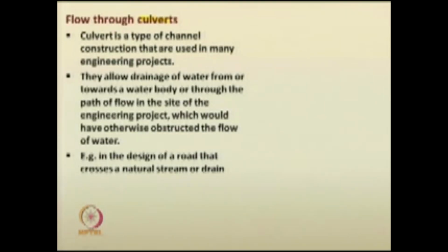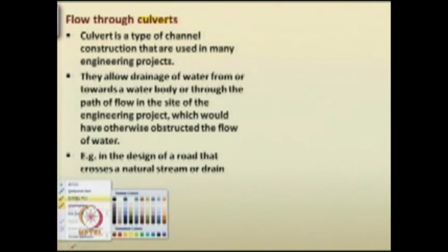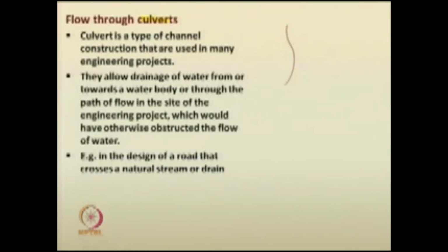A culvert is a type of channel construction that is used in many engineering projects. If I just try to draw it for your benefit: if there is any natural drainage, a small drainage or channel that is draining water from upstream to the downstream, and there is an engineering project that demands passing through this drainage, it is not advisable to block this natural drainage.